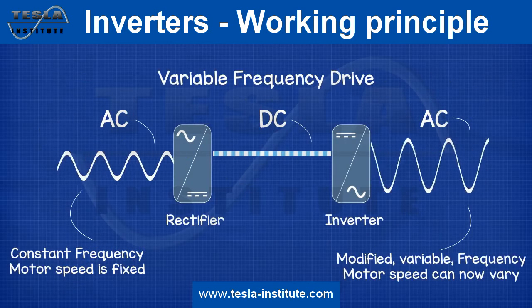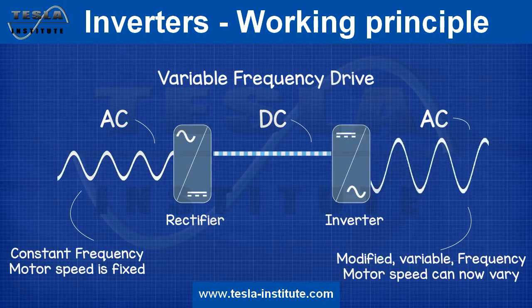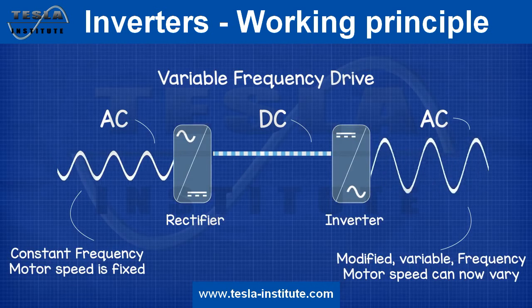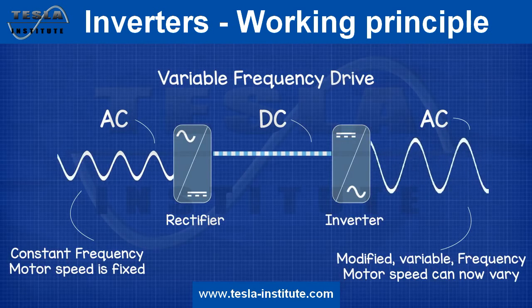In this application, the inverter is coupled with a rectifier, and the AC power which comes in is converted to DC and then back to AC, but the controllers will change the frequency of the sine wave pattern. And by manipulating this, we can precisely control how the motor behaves. And when you join this to a fan or a compressor, etc., then you can precisely control how that performs also. This is partly how the Danfoss Optima Plus inverter condensing unit works.